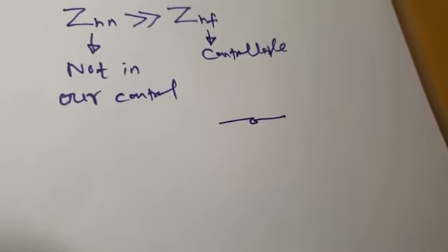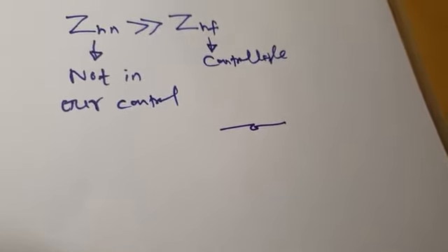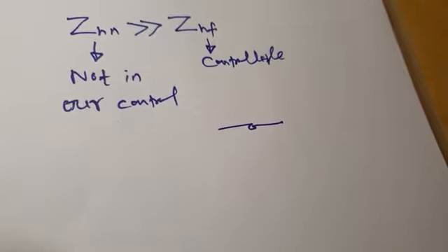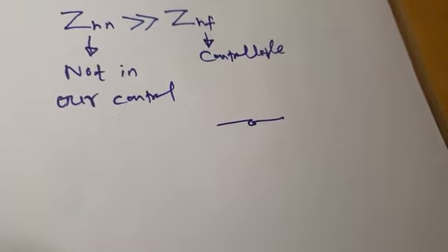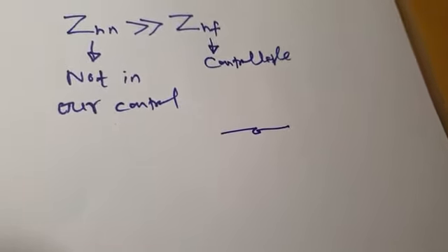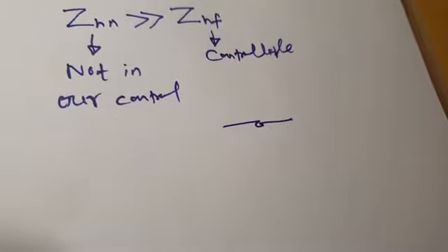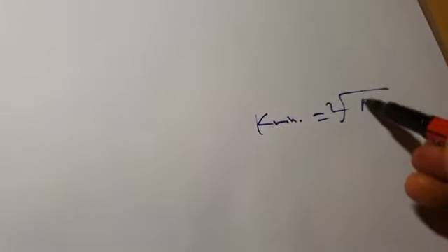That means the reactive power compensation that the filter has to provide should be governed by that equation. Then we substituted that condition into the original equation and found the minimum cost of the filter, K min, which is under root of 2 under root of AB.